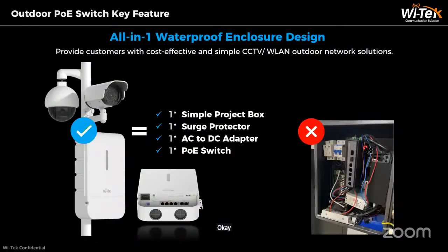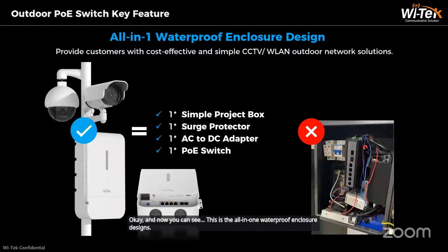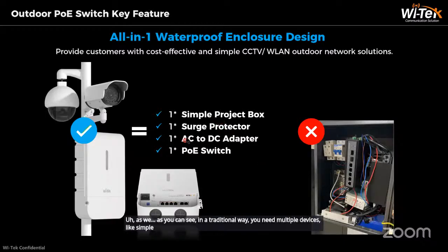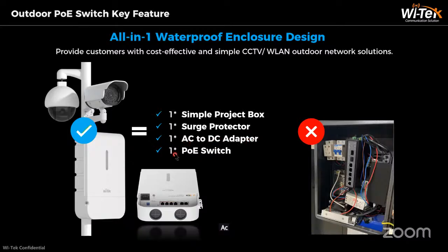Okay, and now you can see this is the all-in-one waterproof enclosure design. The design idea is meant to replace the traditional way for outdoor CCTV projects. In a traditional way, you need multiple devices like a simple project box, surge protector, AC to DC adapter, and PoE switch.